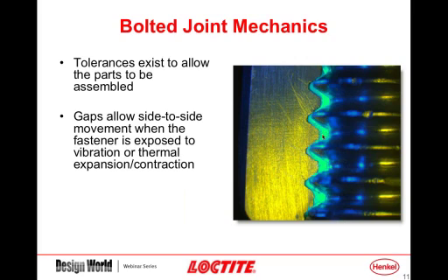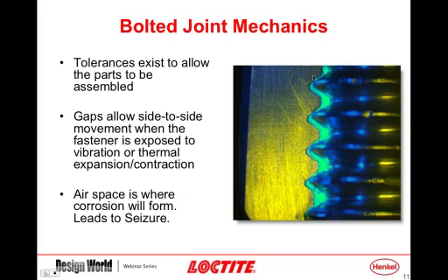This open space, which you can see with the fluorescent material, is the helical space that occurs between the nut and bolt. This is where you can get some movement under various conditions, and this can cause loosening, or it's a root of how loosening occurs once you get movement in that area. And that area is also a helical path where you can get leakage, and we talked about a third type of failure, and that is corrosion, where you can't get the fastener to be disassembled. That occurs in this area. So we're going to revisit this area as we move through this presentation.